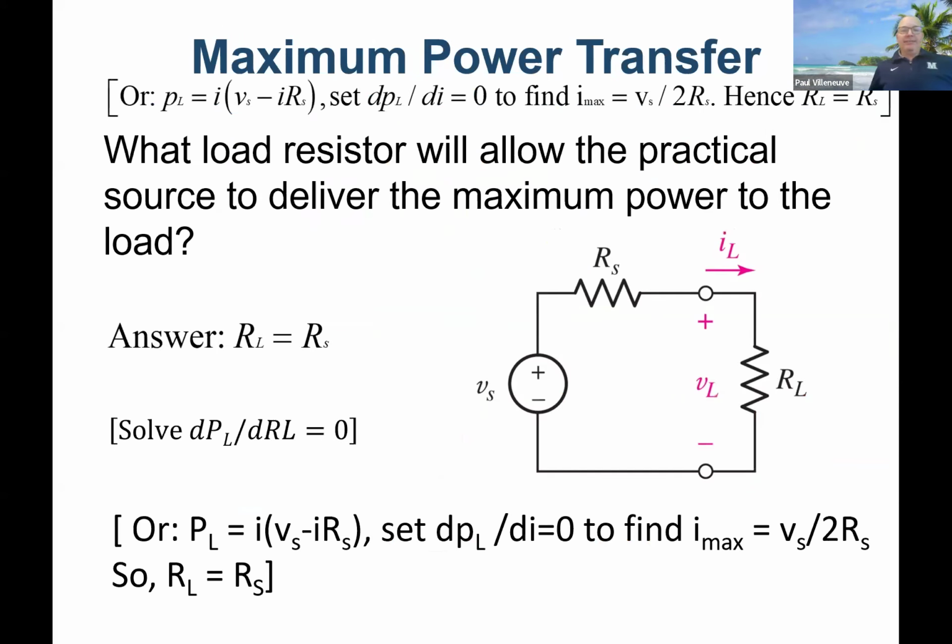All right, last thing. We love ourselves some math, right? Max power transfer. What does max power transfer say? Yes, sir? R load is equal to R, the source resistance, you get the maximum power out. Max power transfer occurs. That's exactly right. It's not when it's 0, because there is no max power transfer, right? Because V squared over R or I squared times R, right? When R is equal to 0 is not going to get you anything, right? So you actually have the ability to calculate that.